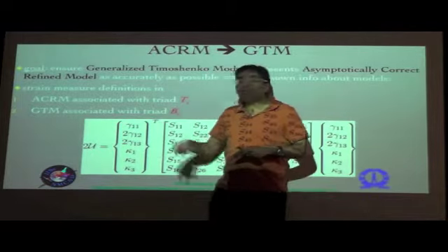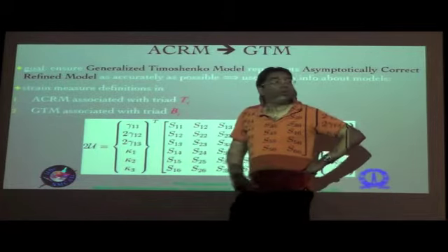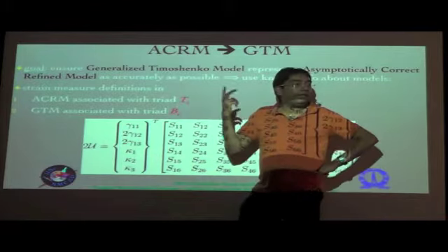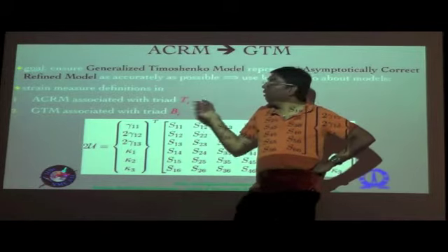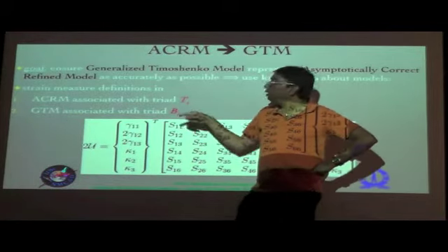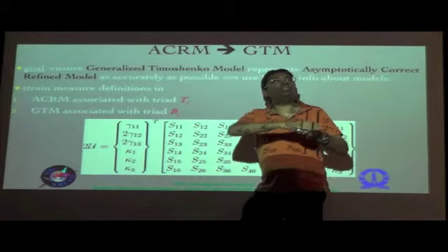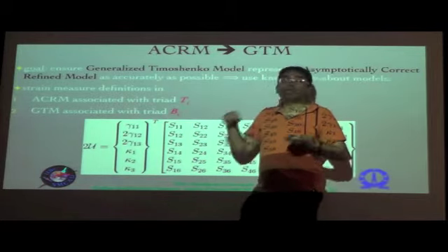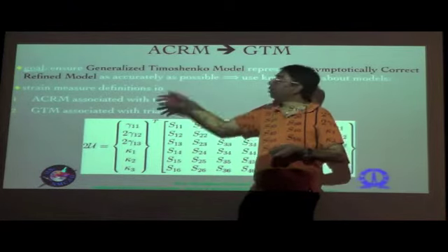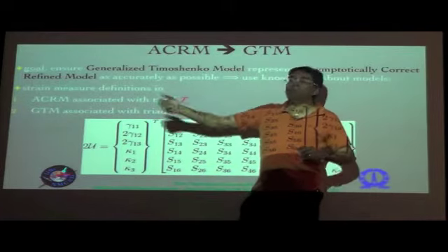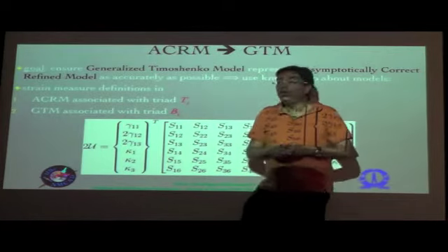On the other hand, if you want to explicitly introduce those artificial additional 2 degrees of freedom, 2 gamma 1 2 and 2 gamma 1 3, instead of dealing with a triad Ti, we have to deal with a triad Bi. And this we have seen earlier also in the beam kinematics. We have given various simplified examples. We have shown that we can introduce the B1, B2, B3 in such a way that it is the overall rotation of the cross section, and therefore explicitly 2 gamma 1 2 and 2 gamma 1 3 are contained as coefficients of B2 and B3 terms when you are expanding out the position vector of any arbitrary point in the cross section, or for that matter a point on the reference line.